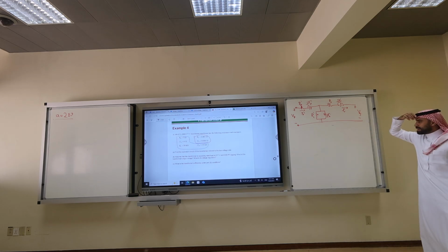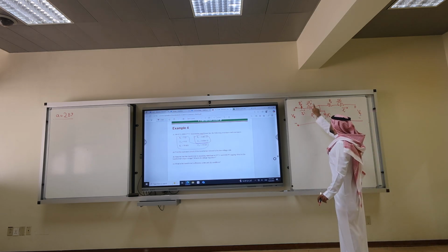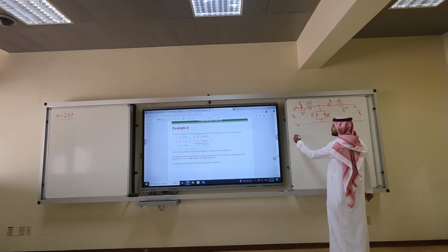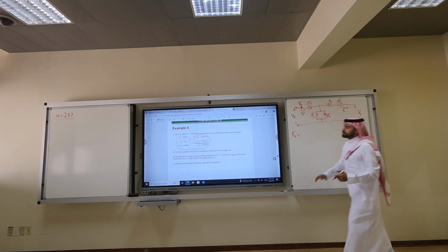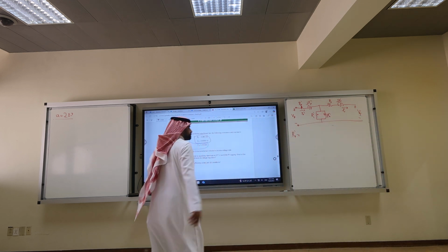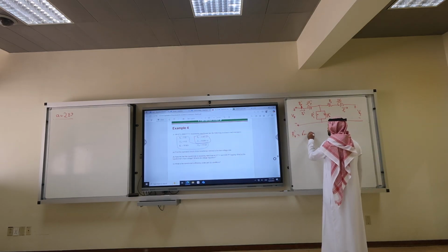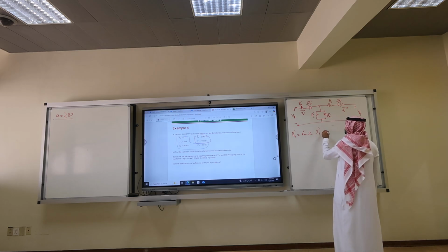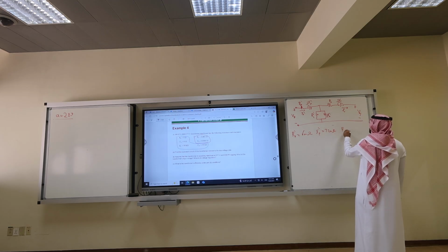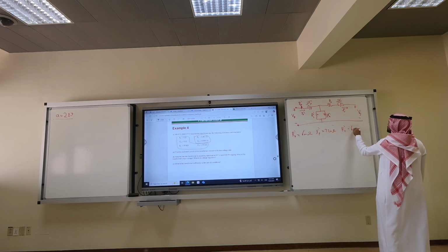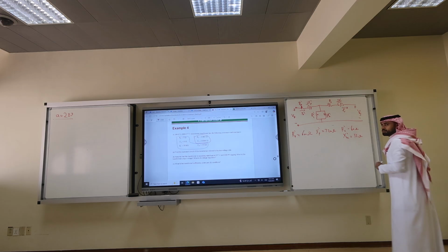Step number one, I need to calculate this, that. So what is RP prime? Give me numbers. Divide by a square. Divide 5 over a square. 6 milliohm. What is XP prime? 7.2 milliohm. What is RC prime? 60 ohm. What is XM prime? 12 ohm. Get it?